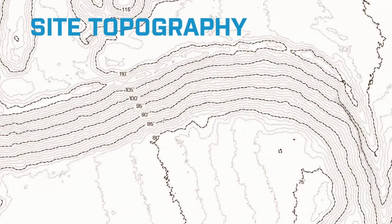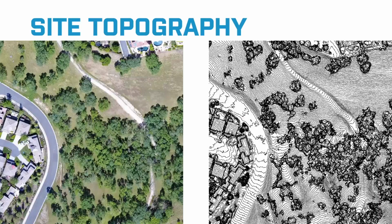And with that 3D model, you can extract topographic lines, so you can cut them horizontally and then get a fairly accurate topographic map, which is great for understanding the slope and the grading and drainage of a site. So here's an example of the orthomosaic map that you get with a drone, and then a topographic map next to it. And you can see where the trees aren't, it would be a very useful and accurate topographic survey.